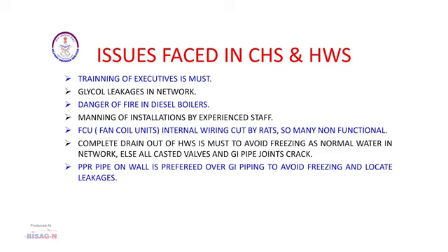Apart from FCUs, we have wall panels also, which dissipate the heat. Complete drain out of hot water supply is also a must, because in winters the provision of hot water supply is done, but if you leave the water in pipes at night, then all your cast walls will crack, resulting in a major problem which needs to be addressed. Then only this system can run again.